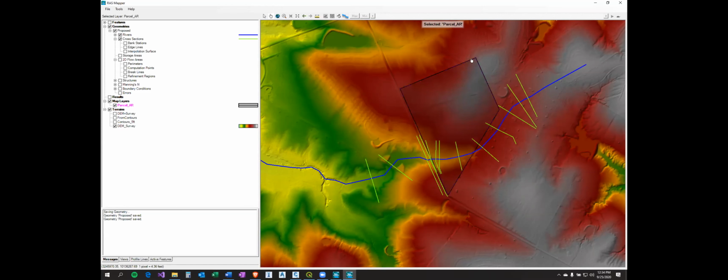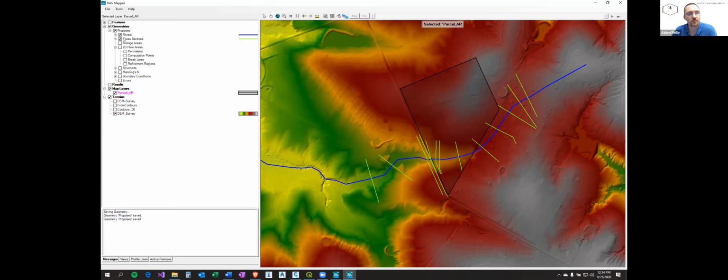So if you're going to edit it in here, you want to be wary of what file you're referencing for your layers in here. Like everything in the geometry up here, these aren't referencing the shapefile. These are in the RAS geometry file. Any of the map layers, those are the shapefiles.